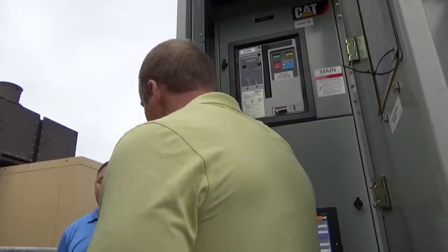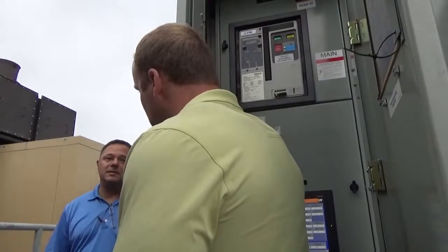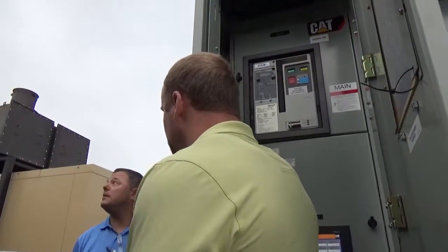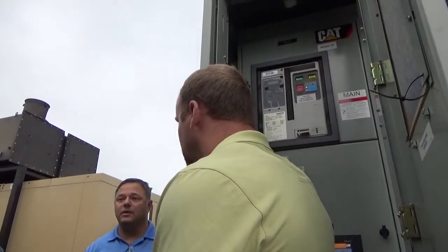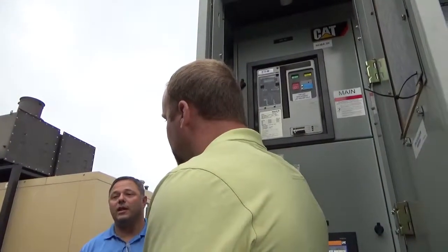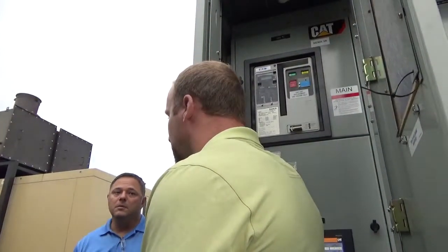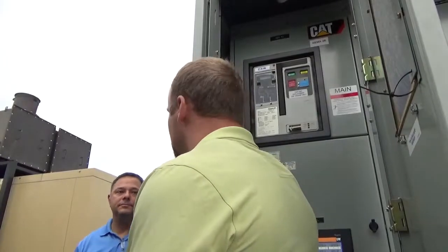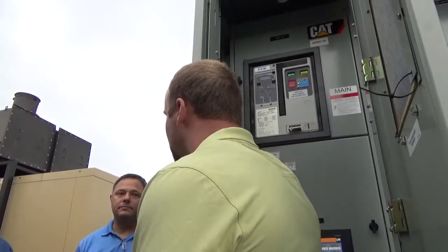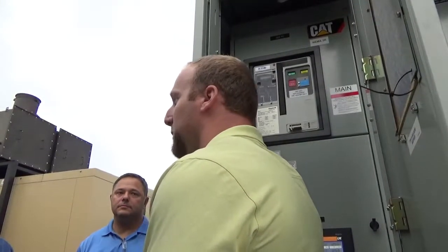So there's a difference between power outage and testing. Yes. So the power outage, that might be running for 2 days straight. And if they're wet stacking for 2 days straight, it's bad. I mean, I hate to throw another scenario out there, but look at the earthquake in '94. How much emergency power ran forever.